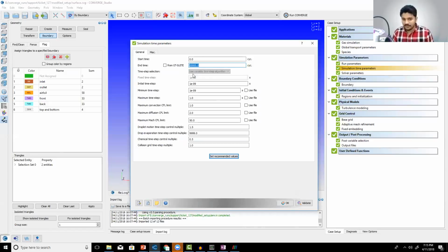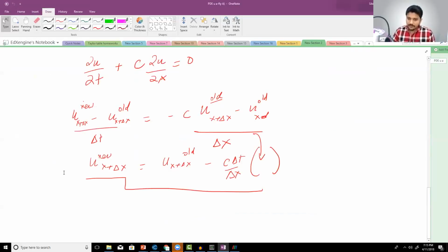That is based on experience. And then there are certain values like, what is the time step size? Well, what is time step? If you see in this equation, you have time step, and this right here is a computational mesh. That is why it's very important to learn to code CFD, because when you're coding CFD, things like time step, CFL number, stability criterion, you will understand very quickly because you're coding it on your own. If you're using an application package like ANSYS, if that is your first interaction with CFD, then you will not be able to learn these terms.